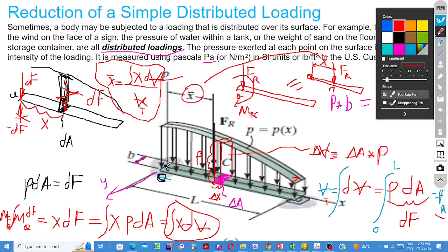But from this analysis, from such an interpretation, we can conclude that the coordinate of the line of action of the resultant force with respect to the reference point, that force representing the total effect of the distributed load with respect to point O, is equal to the coordinate of the center of the volume. Which volume? The volume under the load curve.